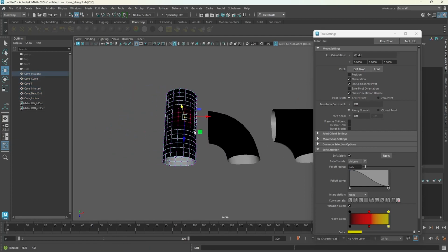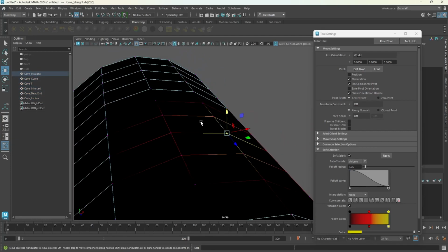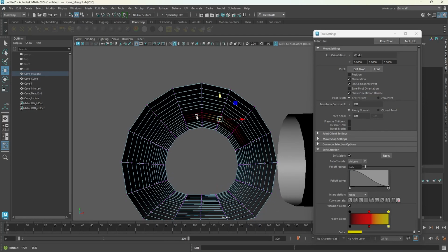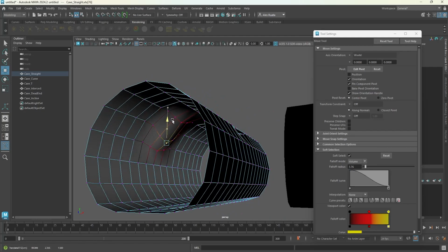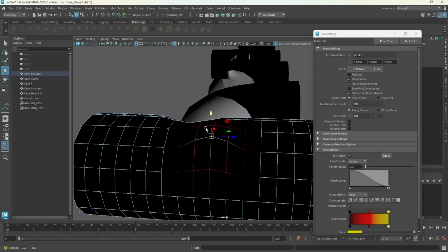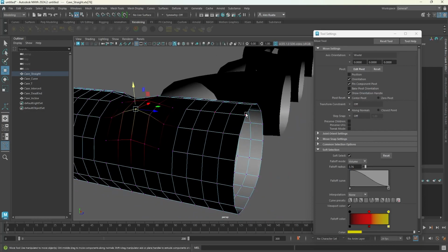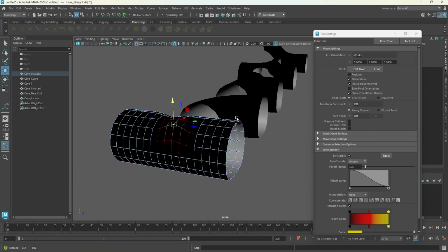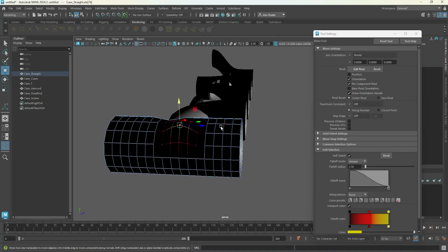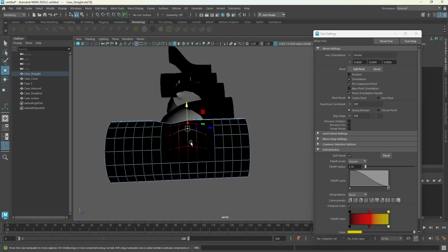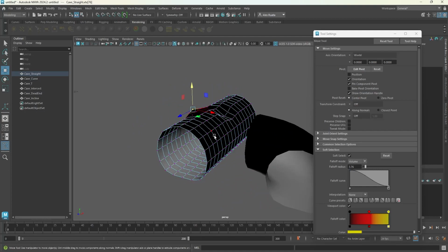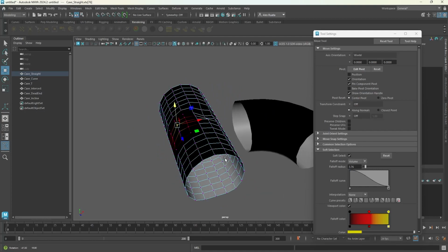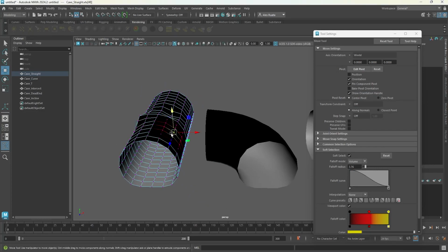Our next step now is going to be to create some irregularities for the cave so that it doesn't feel like such clean computer-generated tubes. We're just going to be playing around with soft select here and making some irregularities. Important to note that all the irregularities I make, I am not going to mess with the edges at all, because if I mess with the edges, then I ruin the tiling fit-in-together effect of the modular workflow in the first place. So any changes that I make to the soft selection, any irregularities I make into the cave, it is going to be in the middle of all my pieces and not at the edges. So here we go.